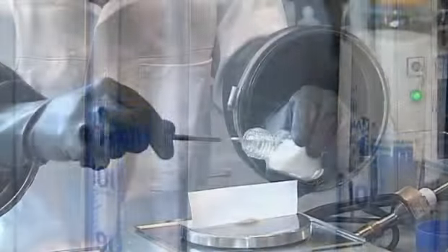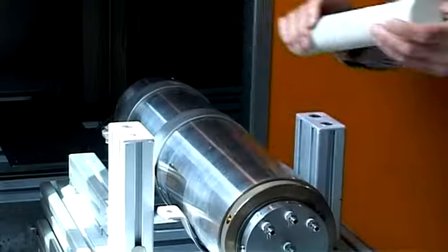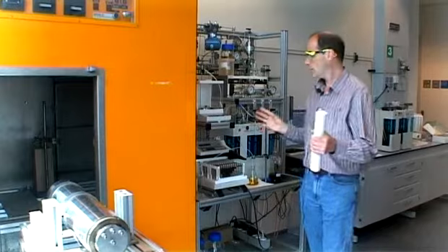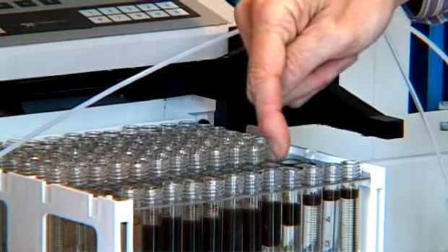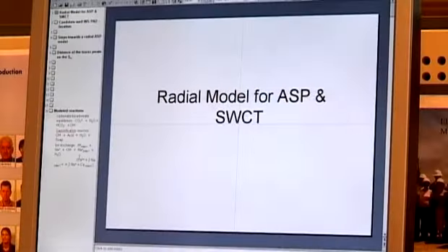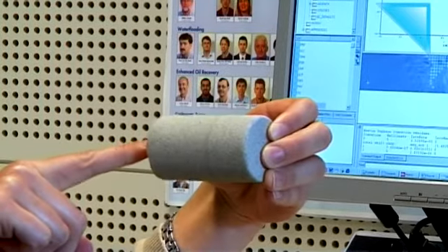water. Then a polymer material is added to increase the water viscosity, and a core flow test is performed to see the efficiency of the ASP fluid in mobilizing oil. The next important step is computer simulations. The computer simulations we are running to understand and get a feeling for how much extra oil we can mobilize with ASP. We simulate first a core flood experiment.